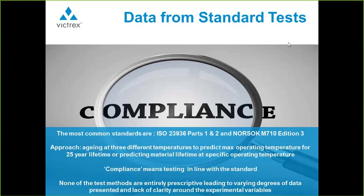Introduction. So yes, as I mentioned on my introduction slide, the NORSOK M710 and ISO 23936 standards are probably the most frequently referred to standards in this field, and both of these deal with gaining an understanding of how a material, polymer material or elastomer, will perform when aged in contact with media used in the oil and gas industry.